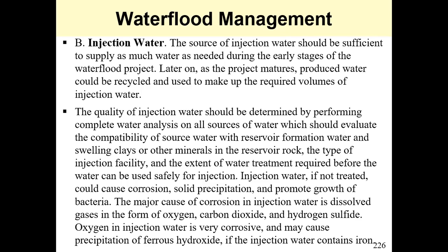So you will need to test for the quality of your injection water by doing a complete water analysis, because you must show that your source of water is compatible with the formation water and the formation, so that it won't lead to swelling of clays around the well. This would impair your injector well performance.